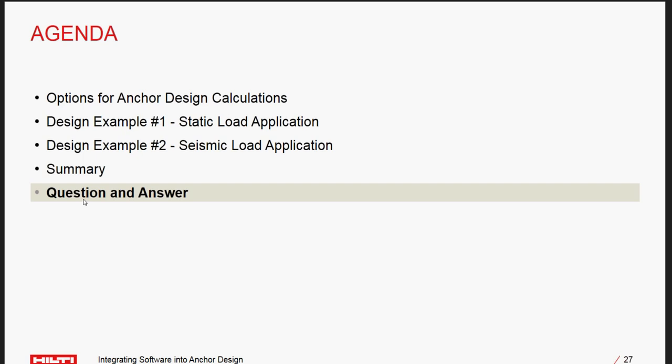Now, something to note, we do get questions here, when we input this overstrength provision or this provision D in seismic design, the software is not going to tell us what omega naught factor we've used. So you may be familiar, it's probably 2.5 or 2, depending on what your application is. It's not going to tell you that. All it's saying is the user selected the overstrength provision, so the user should have inputted that omega naught factor into their factored design load, or their factored service loads.